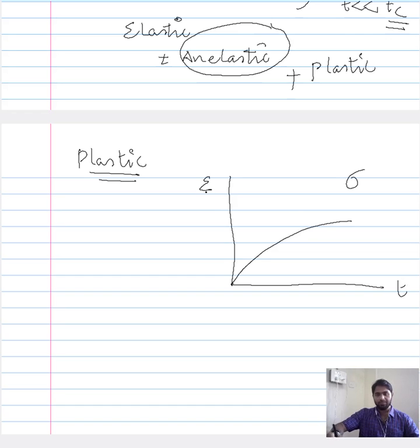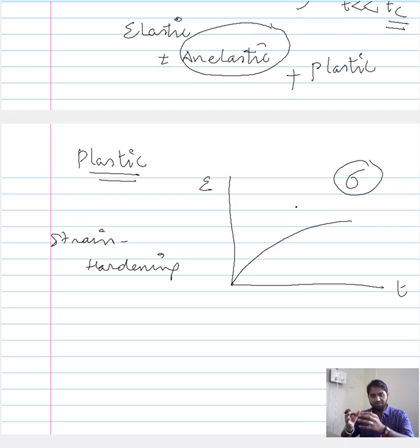In case of the stress strain curve, we refer to it as the strain hardening. So whatever I have been talking about is nothing but the strain hardening. In order to continue your plastic deformation, once you have a certain amount of dislocation density, the amount of stress required increases. However, in our case, the stress is assumed to be constant, and therefore the amount of strain exhibited by the material once the plastic deformation has occurred decreases, and this is what leads to the decelerating creep or the transient region.